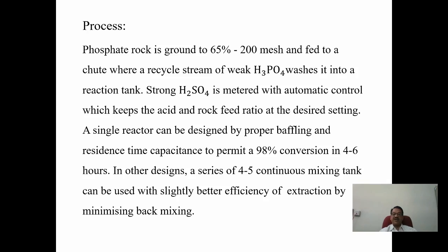Strong sulfuric acid is metered with automatic control, which keeps the acid and the rock feed ratio in the desired setting. A single reactor can be designed by proper baffling and residence time capacitance to permit a 98% conversion of phosphate rock into phosphoric acid in 4 to 6 hours.